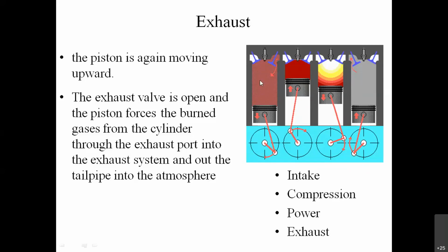Whatever air you have taken, 1/20th of that actual volume is the compression ratio for the CI engine, whereas the compression ratio in case of the SI engine is 1/8 of the actual volume of your air-fuel mixture. So here only air is taken inside the cylinder and compressed. Because of that compression, the air is heated.